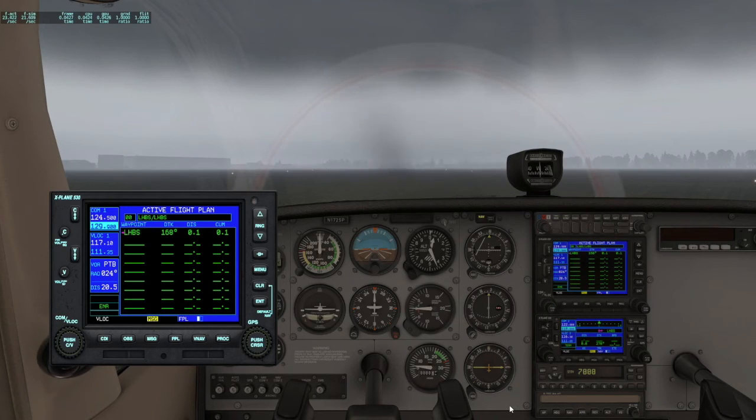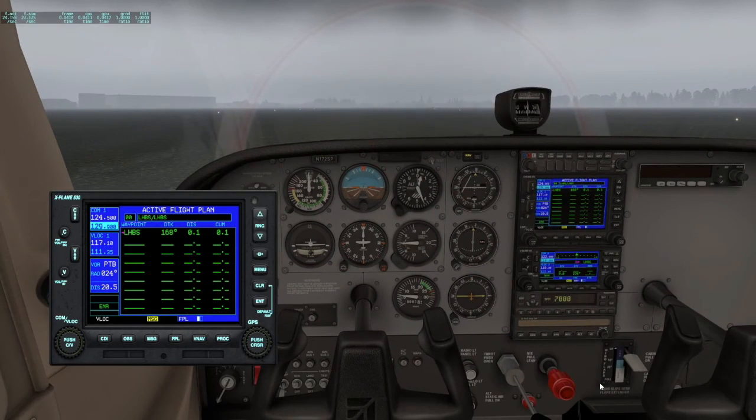All I need to do is just climb up to 3,000 feet, and I have to stay below 3,500 feet because this airfield is very close to the Budapest International Airport, and the TMA in that area where that airfield is starts at a lower level of 3,500 feet, so we have to stay below the TMA, as you obviously know. Okay, so to get the aircraft ready, I'm going to put flaps 1.